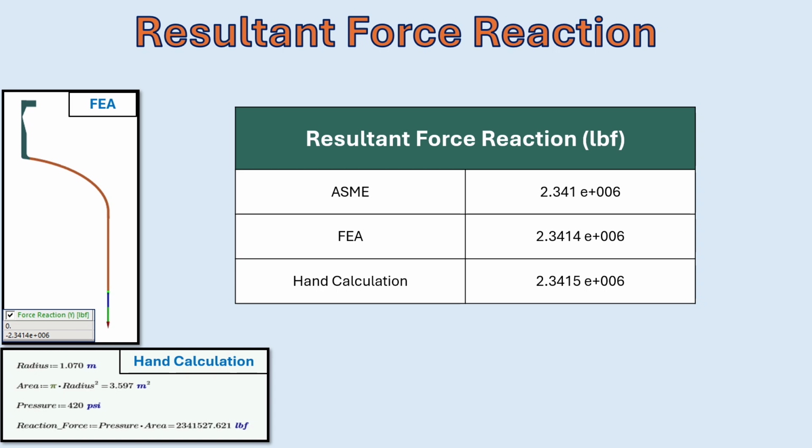Next, we validate the finite element model by comparing the resultant force reaction at the remote boundary condition. The values obtained from ASME, from FEA, and from a very basic hand calculation considering only the pressure load are in excellent agreement, which confirms that the FEA setup is correct.